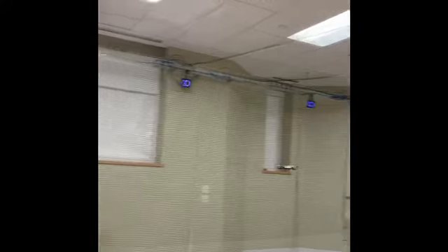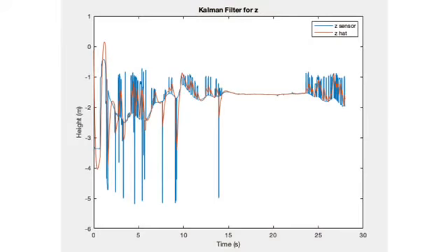2 meter height command. However, this takeoff does not appear to be the most energy optimal, as there is a lot more height overshoot when compared to the previously used bang-bang takeoff method. This could perhaps be fixed by adjusting the damping ratio and natural frequency values to allow for a longer rise time. Another issue with the initial takeoff could be due to faulty sensor readings.